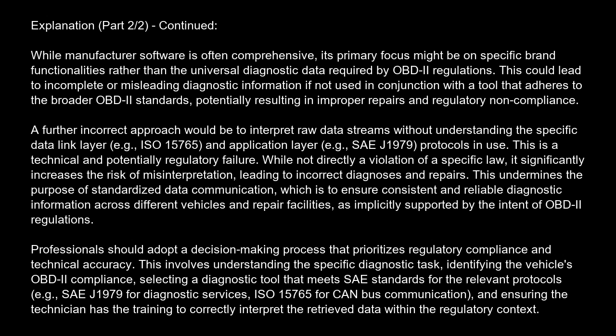A further incorrect approach would be to interpret raw data streams without understanding the specific data link layer, e.g., ISO 15765, and application layer, e.g., SAE J1979, protocols in use. This is a technical and potentially regulatory failure. While not directly a violation of a specific law, it significantly increases the risk of misinterpretation, leading to incorrect diagnoses and repairs. This undermines the purpose of standardized data communication, which is to ensure consistent and reliable diagnostic information across different vehicles and repair facilities, as implicitly supported by the intent of OBD-II regulations.